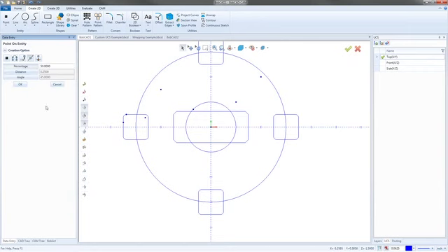The point on entity is just the exact same. This is the best way. If you're just trying to find a single center point for a line, this is the best way to do it. You go to percentage, leave it at 50%, and then click on the line you want to put the point on. It'll snap a point at the 50% mark, and yeah, you'll always find the middle point there.